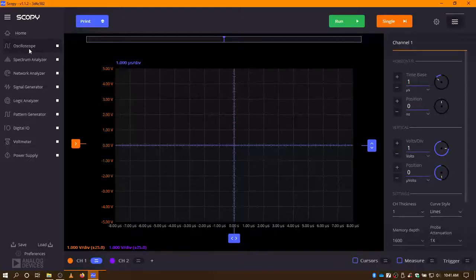One other thing you want to remember about the m2k is the oscilloscope inputs are the same as the voltmeter inputs, as are the spectrum analyzer inputs. So in other words, you can only use one feature at a time. You cannot use multiple features. Okay? Now we'll go into wiring up the oscilloscope and then running the software.